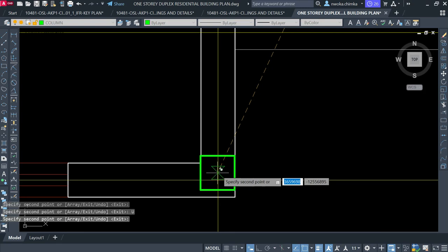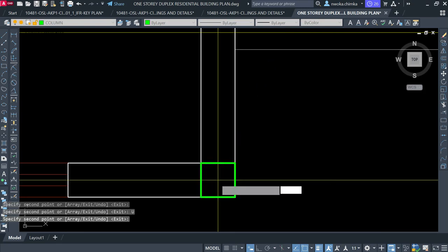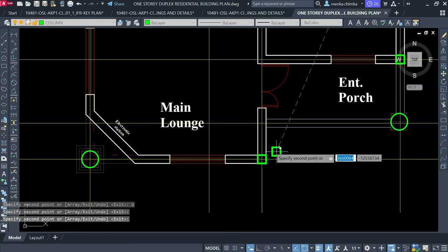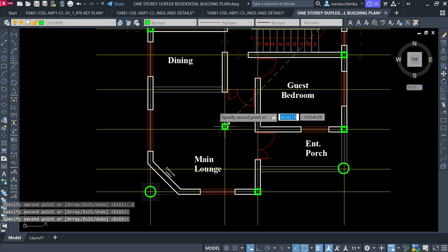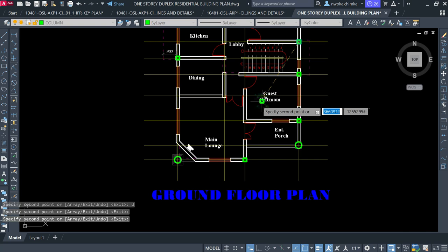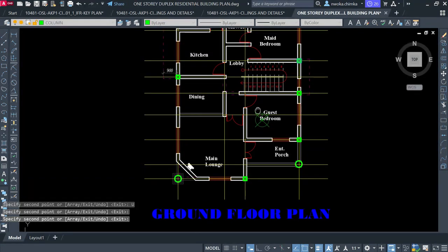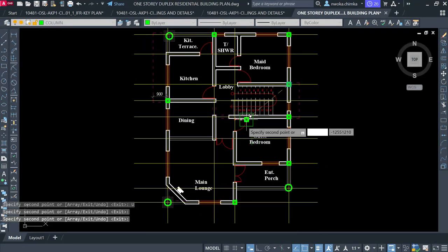So now column position depends solely on you. No one will tell you how to position your column. So that's why you're meant to know how to position your column very well. And if your column points are not well framed, or not at the best position, that's where you begin to have issues in your modeling.